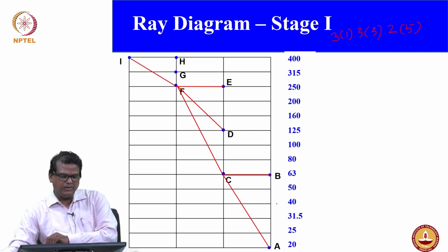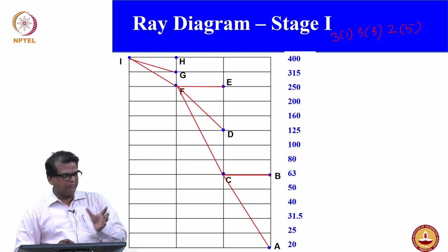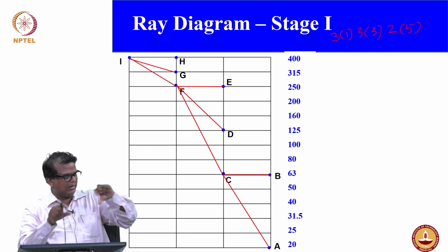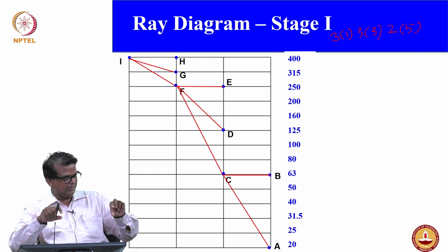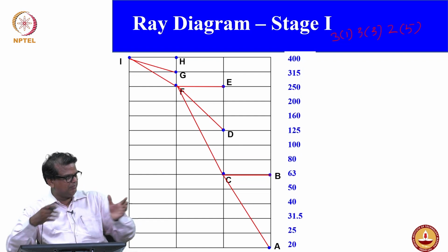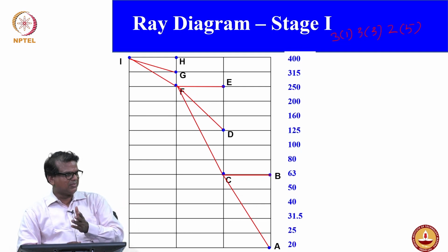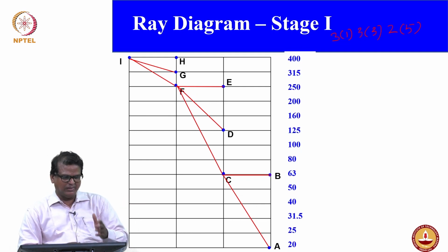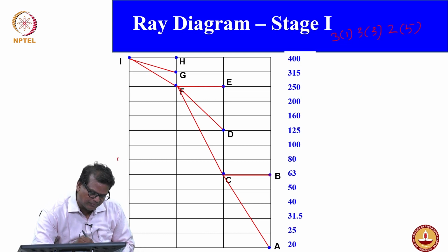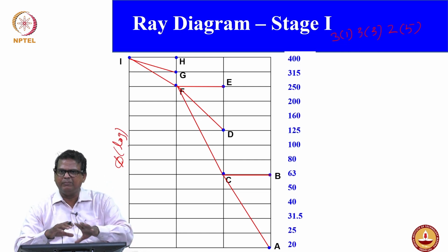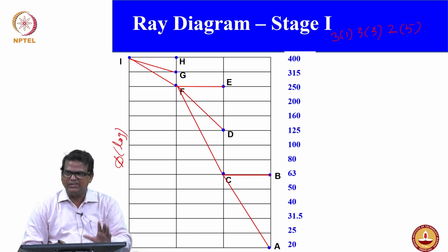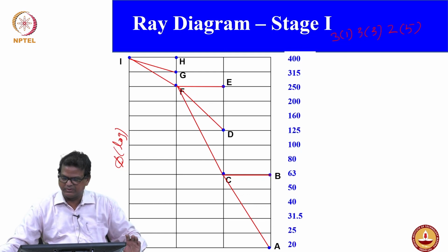Now we'll move on to the next thing, which is G. Remember, apart from the first stage, everything you have to follow parallel, either vertical way or side way. As long as you maintain parallel, that means you are maintaining the step ratio across all the stages. That already we know, and you should be aware of that. The step ratio is on the y-axis in logarithmic scale. Okay, it's in log, but for our convenience, for understanding purposes, we have made it a linear diagram.